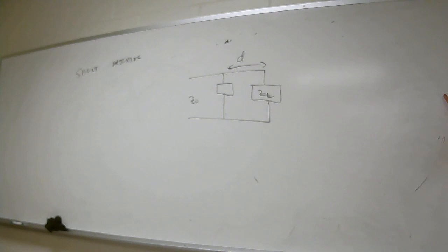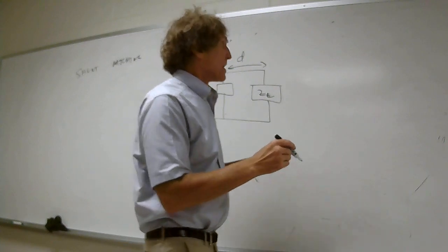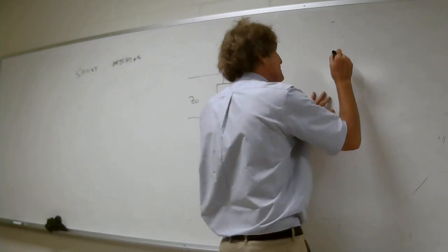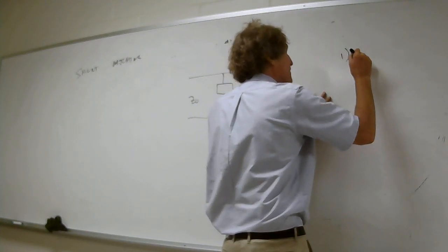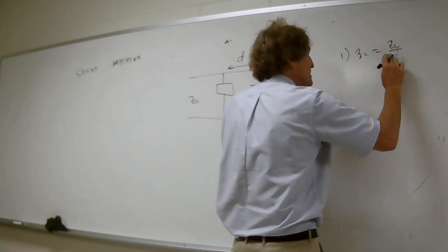Here is a Smith chart, my Smith chart. Here's the one circle. Here's how we do it. I just want you to be attentive. And this is with elements. So the first thing is we're going to find ZL, which is capital ZL over Z naught.